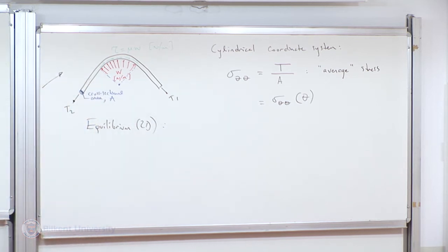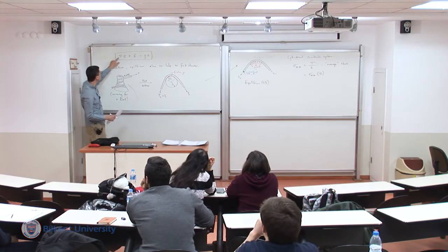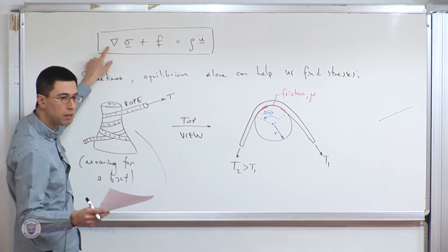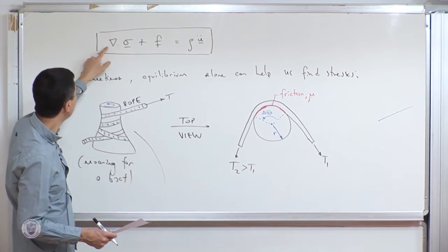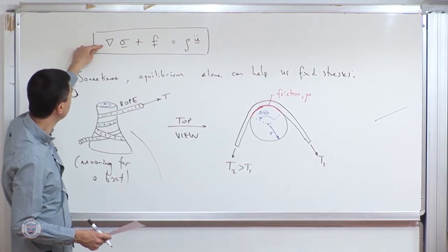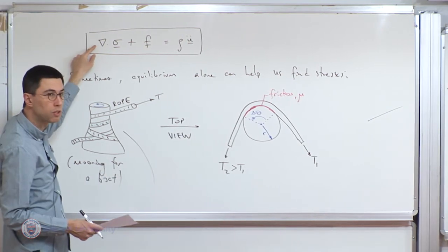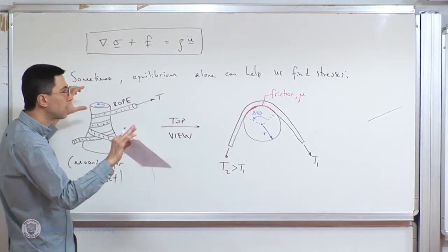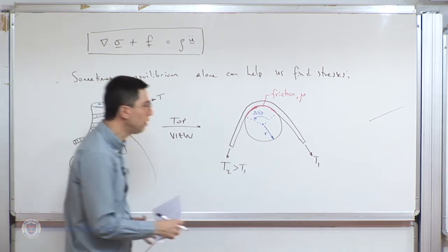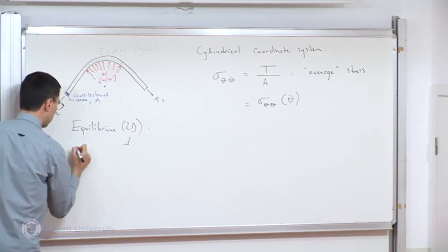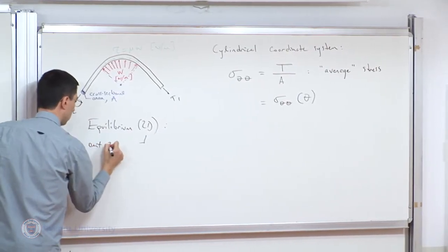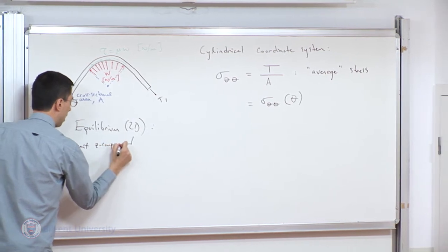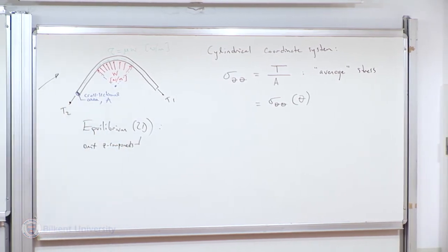So eventually, as I expressed at the very beginning of the course when we were talking about divergences, etc. In your online reference, for instance, our reference book, you can find expressions for divergence of stress in, for instance, a cylindrical coordinate system. So when you look at that expression, because it's 2D, first you have to omit Z components. Anything that has to do with Z, you throw away.